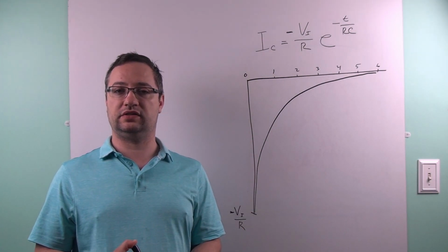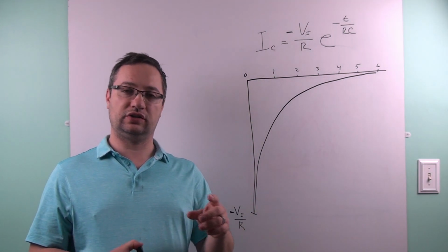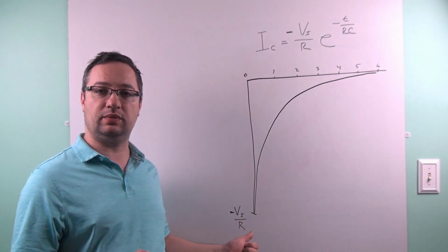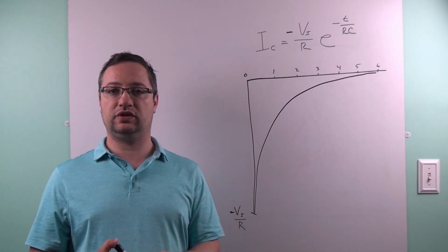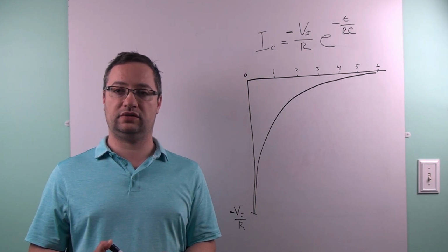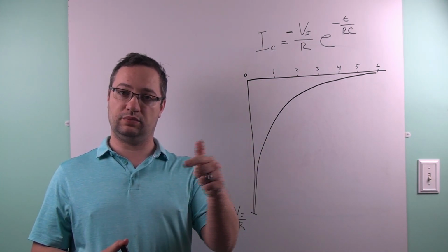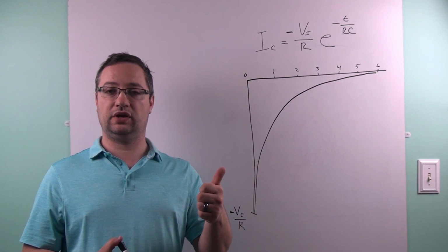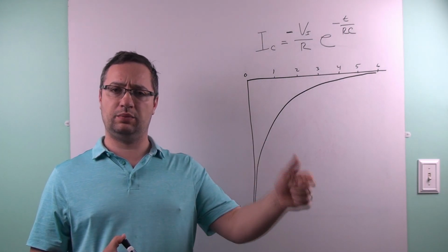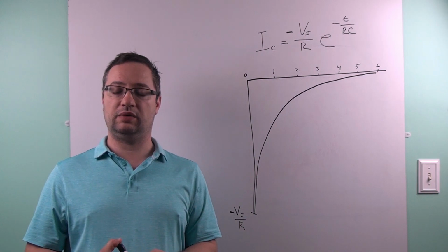from any of this is that the initial inrush, or outrush if you want to call it that, current of a capacitor is the source voltage divided by the resistance that is in line with the capacitor, and that resistance can actually be just the ESR of the capacitor, and that's usually what we refer to as the inrush current. So if you, for example, have a circuit with a bunch of capacitors in it, either for decoupling or bulk capacitor purposes, you can effectively do the calculation of how much initial inrush current you would have when you connect that circuit to a power source.